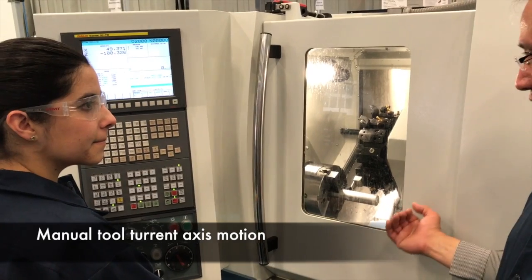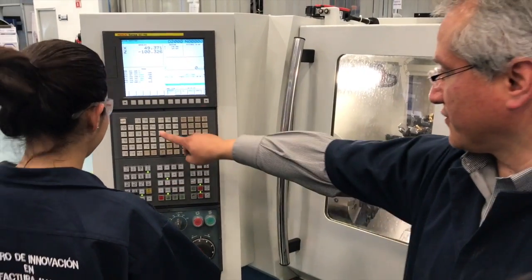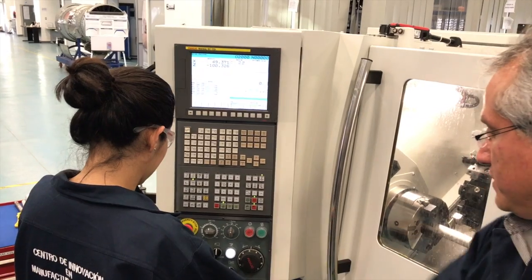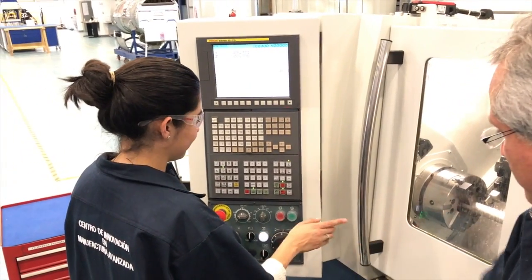Manual tool turret axis motion. This function is used to move X and Z axis while the door is open. The first step is to press reset, then to press jog. Turn the knob key to one position in order to allow the open-close button to start blinking. This will allow you as a user to open the door manually.